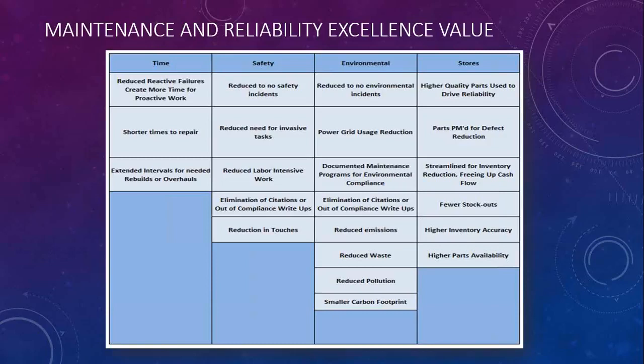But normally it's air leaks. Going out and fixing air leaks is the quickest return on investment. You can spend a month doing air leaks and you'll get, probably 3 to 10 times return on the investment in 1 month if you just spent time doing that. So I would say the Ultra Probe out of all the technologies is the quickest to return on investment. All right. And that's just fixing air leaks. That's not everything else it can be used for.